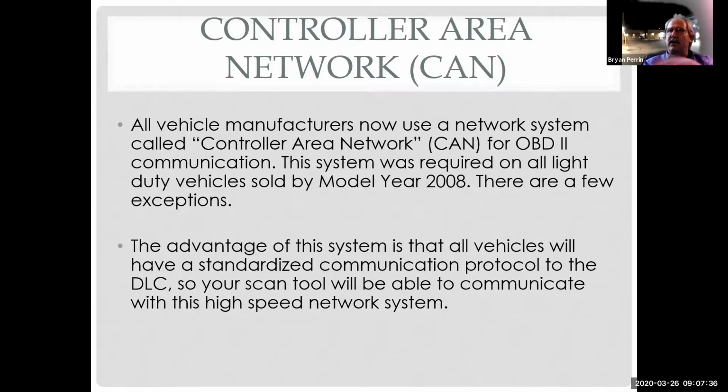So compared to these old systems, where the data was, yeah, this is what it was a minute ago, but it's not necessarily useful for fixing the car right now. It really is much better at what we have today as far as being able to use the scan tool and leverage the information we're getting to actually fix the car without having to go in and do further tests in many cases. And CAN is a big reason for that.